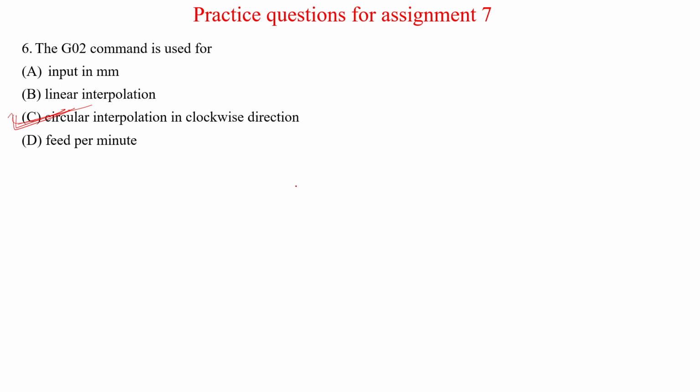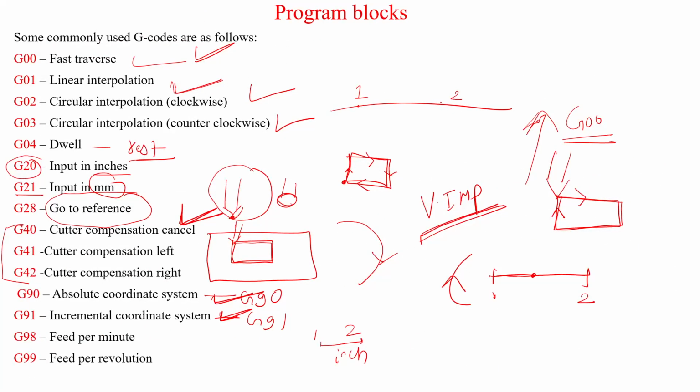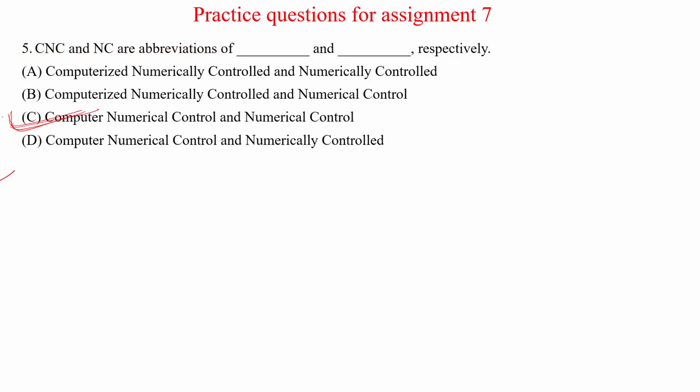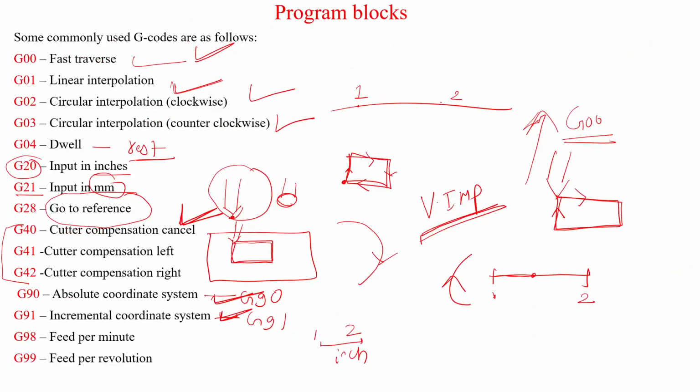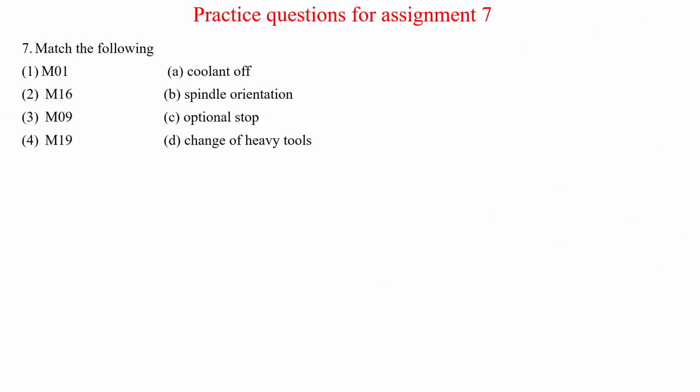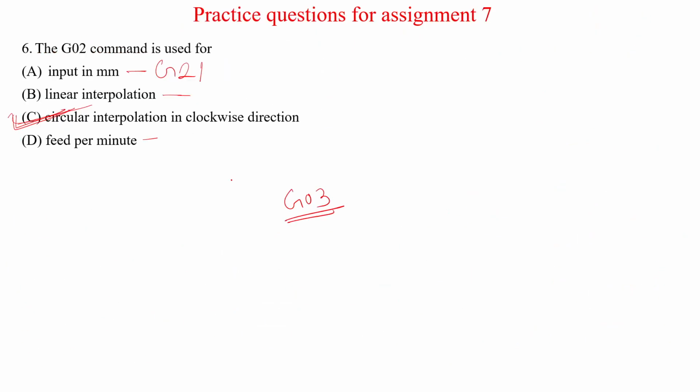And for anti-clockwise? G03. And for input in mm? G21. G20. Okay, fine. G21 only, no? Yes, right. And for linear interpolation? G01. Okay.